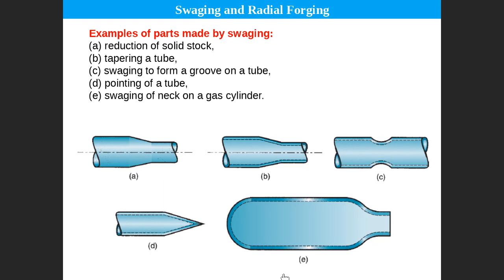When you hammer, the sand redistributes, then the cross section will reduce, and then you hammer, then the sand will redistribute again with the size, and at the same time applying a pressure to maintain the dimension of the cross section. So they put an internal mandrel to maintain the internal dimension, to not collapse the internal dimension.